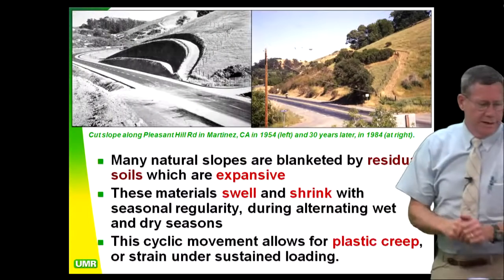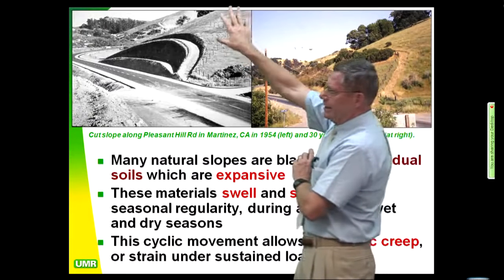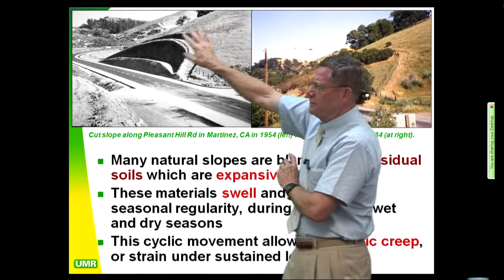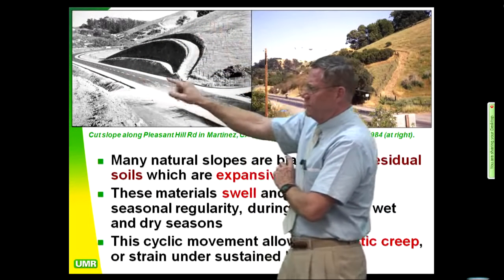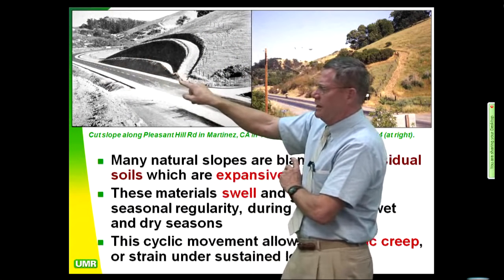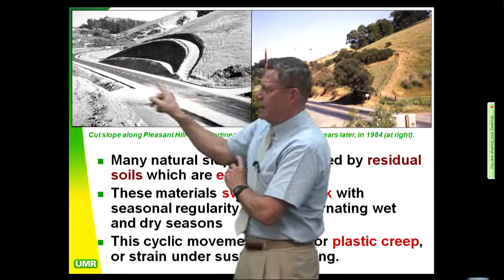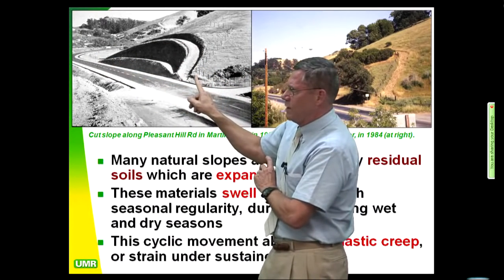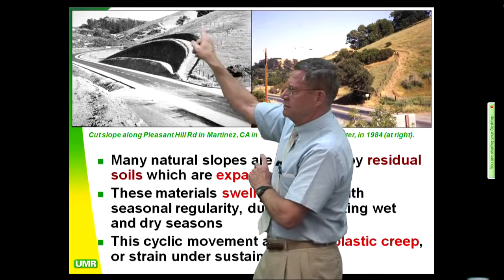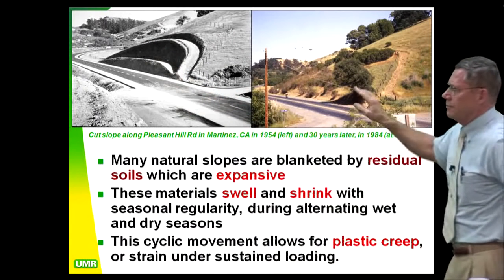And here's a case where we have a slope in a Cretaceous age siltstone, Panoche Formation. It's graded 1954 with a mid-slope drainage terrace that's 10 feet wide, and then a 10-foot high brow ditch going up above the cut. And now I want you to notice this. This is the right-of-way. There's the county or state right-of-way line going up around the cut.